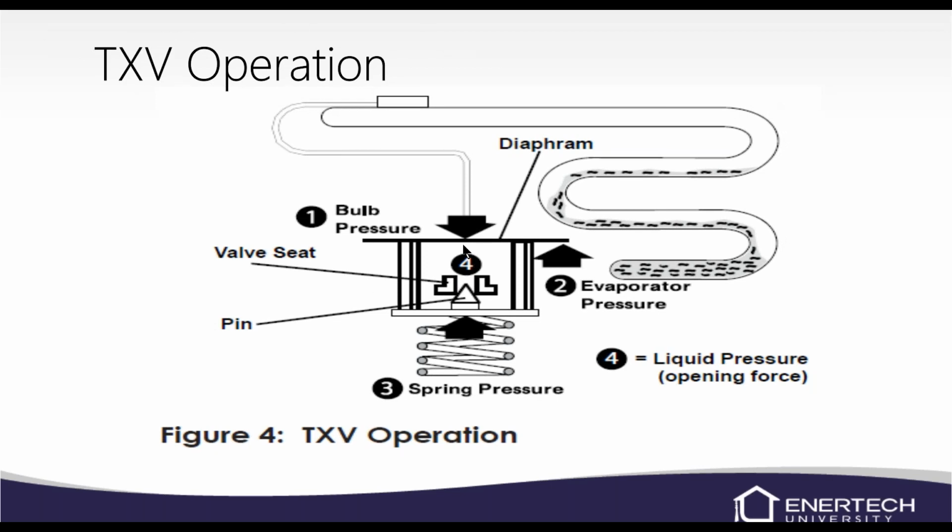I want to show you a little bit about the expansion valve here and what goes on with the valve. These get a lot of negative comments because they tend to stick. And there's nothing really in this valve to really break, other than the bulb might lose pressure. Maybe it rubbed on a refrigerant line, rubbed a hole in it, and the bulb pressure pushes down on the piston, opening the valve up more.